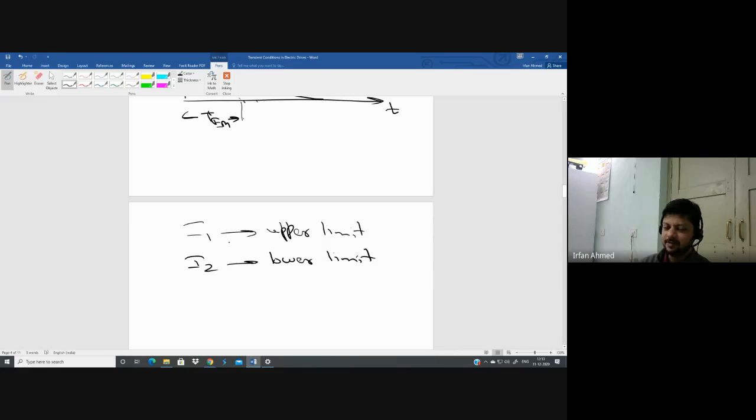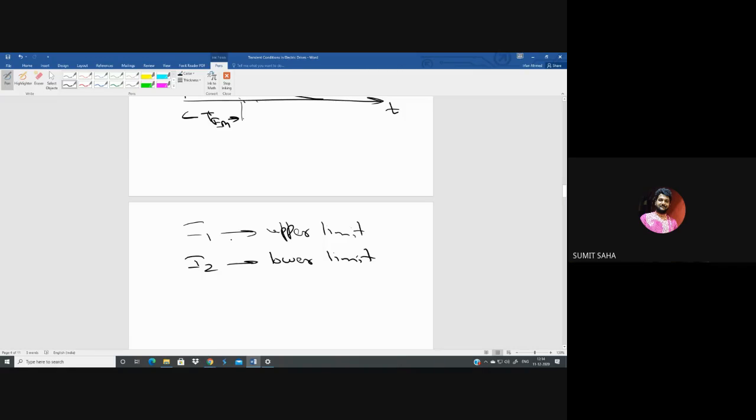Initially armature current will be I1. As the motor speeds up, it will decrease and reach the value I2. As soon as the current reaches I2, we cut out a resistance so that the current once again jumps to I1. Again it decreases because the value of E is increasing, and whenever it reaches I2, we again cut off a resistance. Correct?